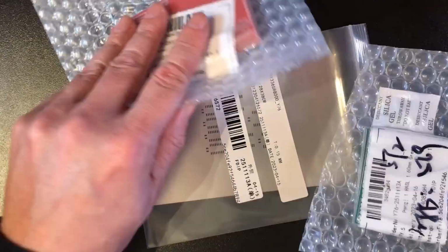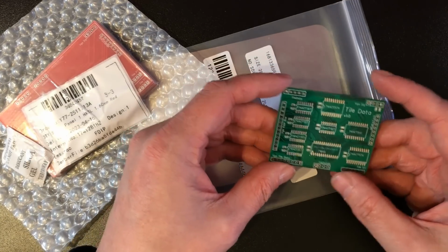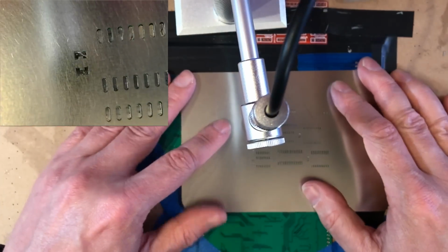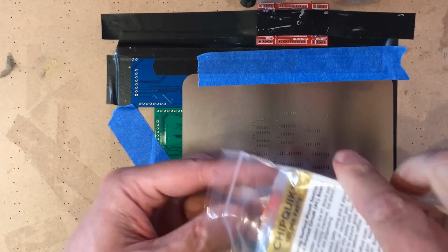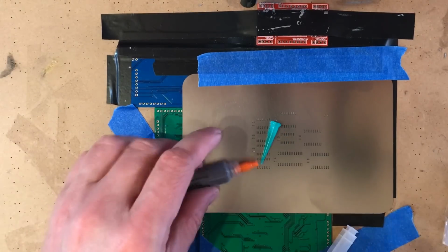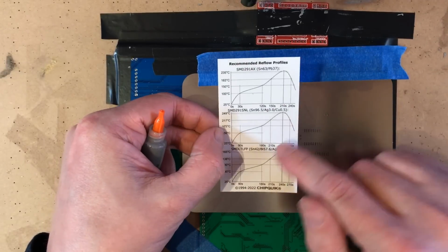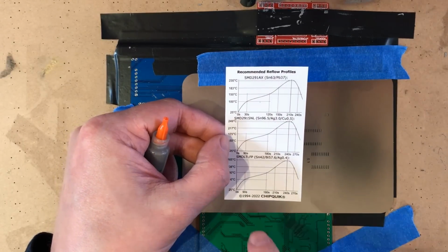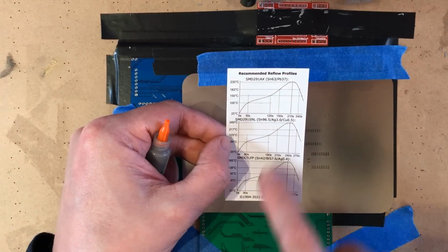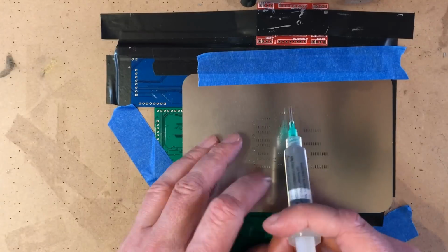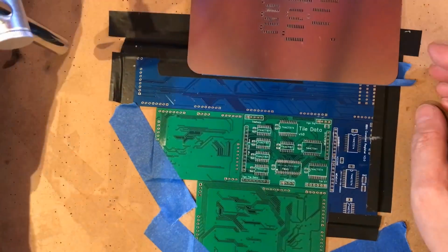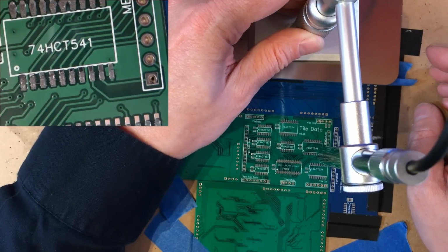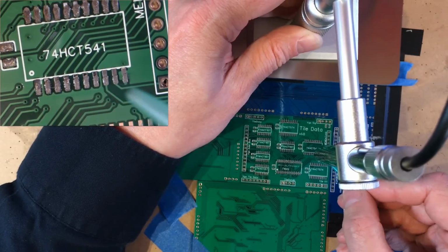Okay, let's take a look at this. It's a very dense little PCB, this one. Now I've got a brand new tube of solder paste. See, this stuff comes with a little graph that shows you what the heating profile is supposed to be. Now I've got the multimeter with the logging capability and a thermometer. It might be interesting to actually try and run this and check what I'm actually achieving. Okay, slightly less than is ideal down there, but